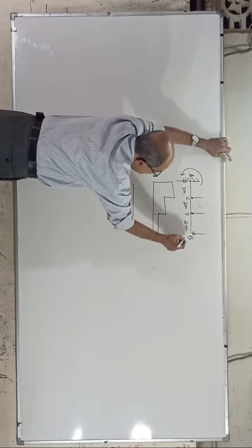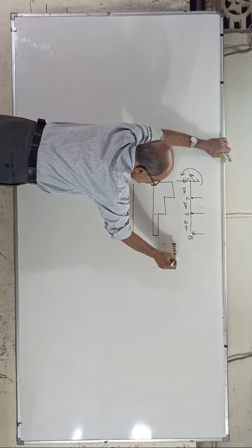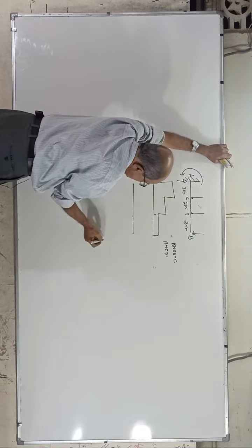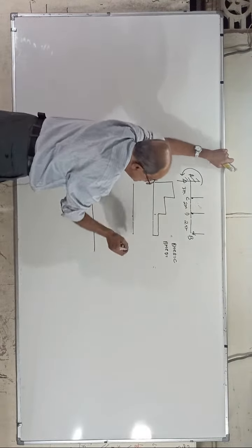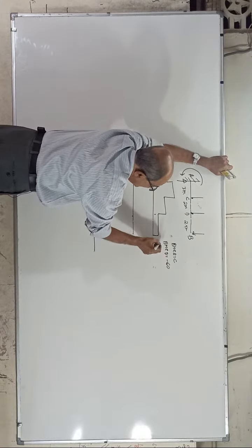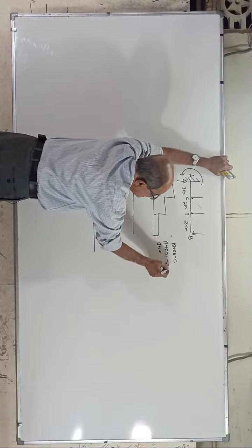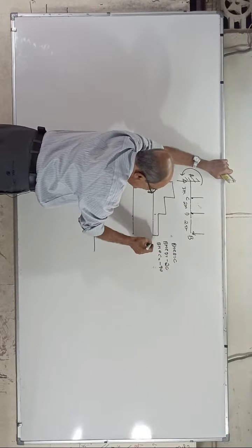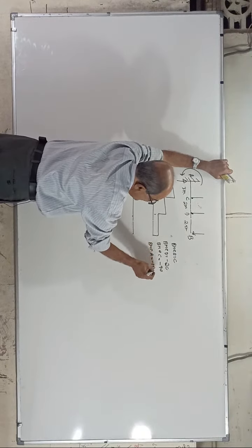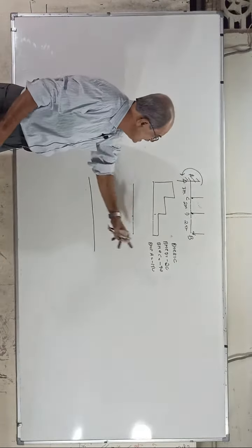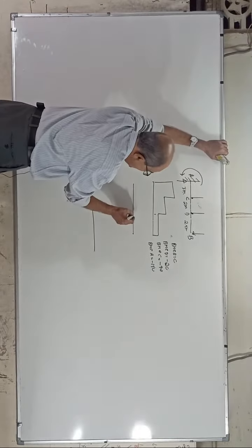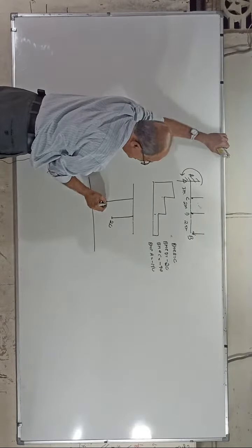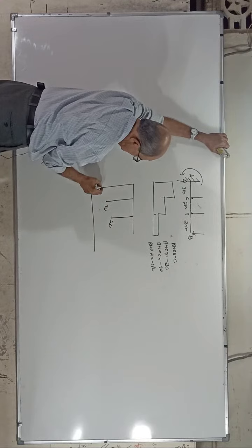See, imagine your BM at B is 0. Why you don't bother? BM at D is, imagine, minus 60. Then BM at minus 60, say minus 20. BM at C equal to minus 90. And BM at A is minus 150 they got. Okay, correct. Why it came, you worry later. Start plotting. They will plot here. How much here? 20. See. Then 90, 150.